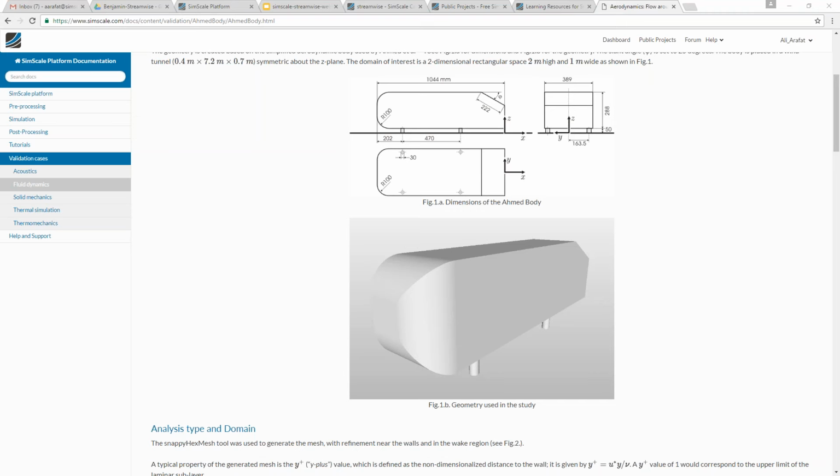Usually in wind tunnel, the cost somewhat scales with wind tunnel time. If you go to a commercial wind tunnel, it's very expensive and you pay by the hour. And in that sense, it's definitely less expensive since you can acquire data in the interesting region a lot faster than you would, for example, with PIV. In reality, I guess it would work that you book like half a day of measurement time, and you can just get more cases done in that time. You can modify your flow situation and optimize with that half day, and with PIV you could maybe only run 1 or 2 cases. So this would be the reality, but in terms of cost per acquired data, it's certainly lower.